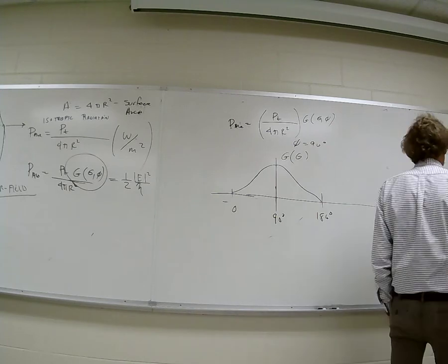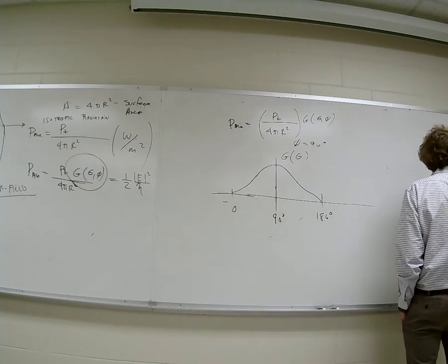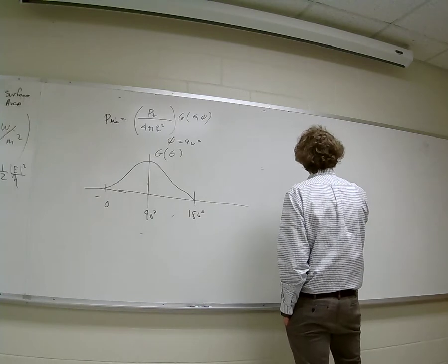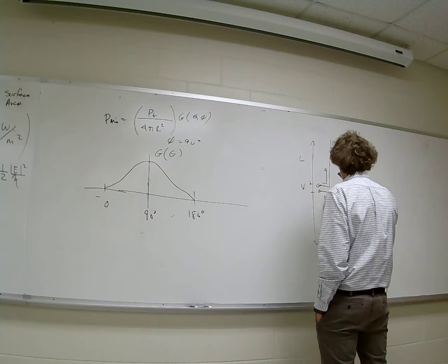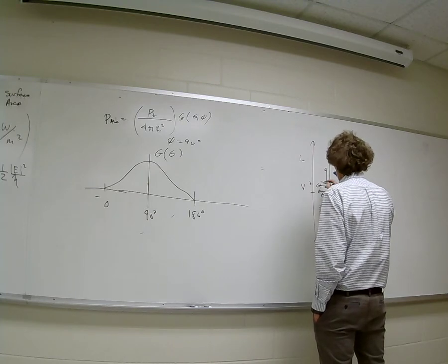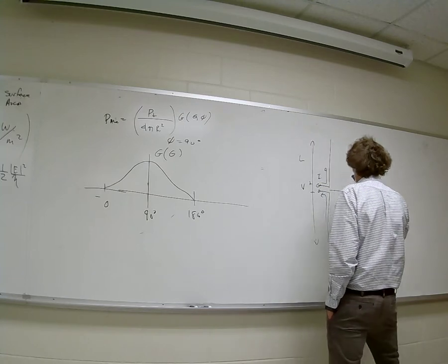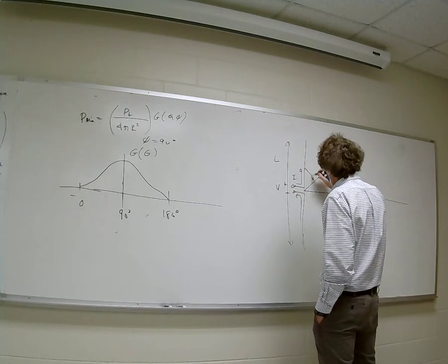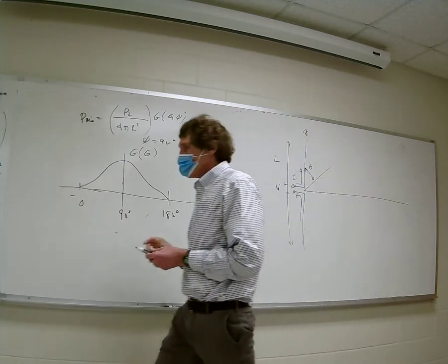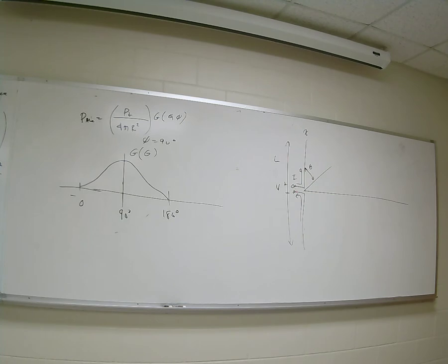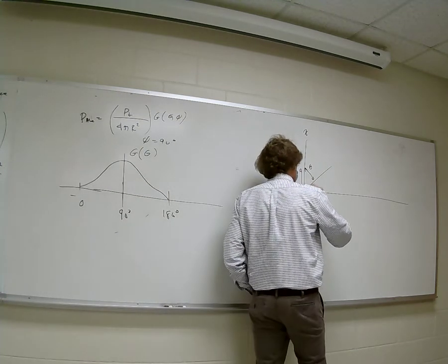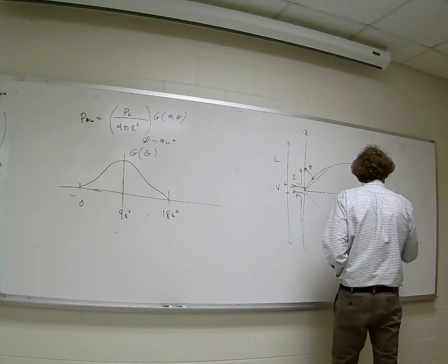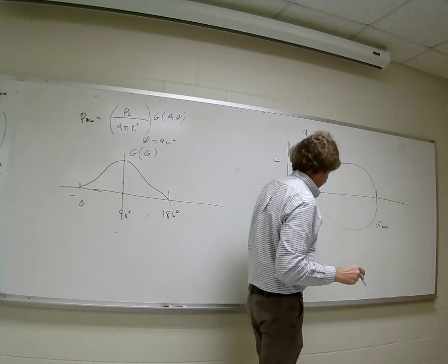If you think about a wire antenna like this, a wire antenna, we'll get there on this one. If I feed it right here with a voltage, plus or minus voltage, it'll develop a current I, like such. It'll have a current signature, but if I looked at how this thing radiates versus radial distance versus this angle theta, call this the z-axis. This is for a wire antenna, it's well known. What you get is something like this. And the max gain would be here. And this would be the power distribution.